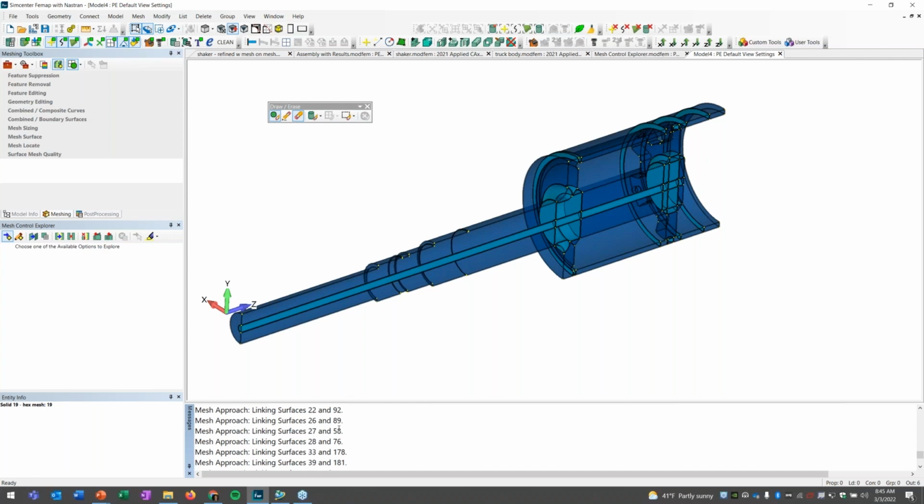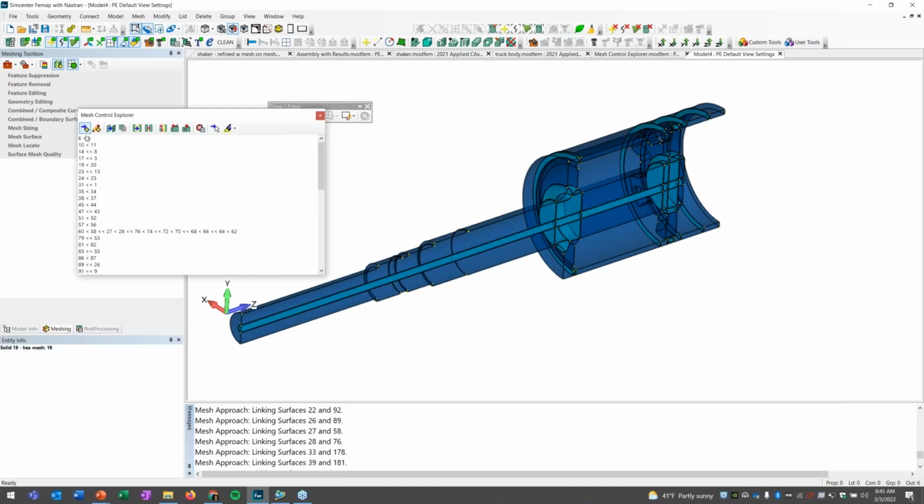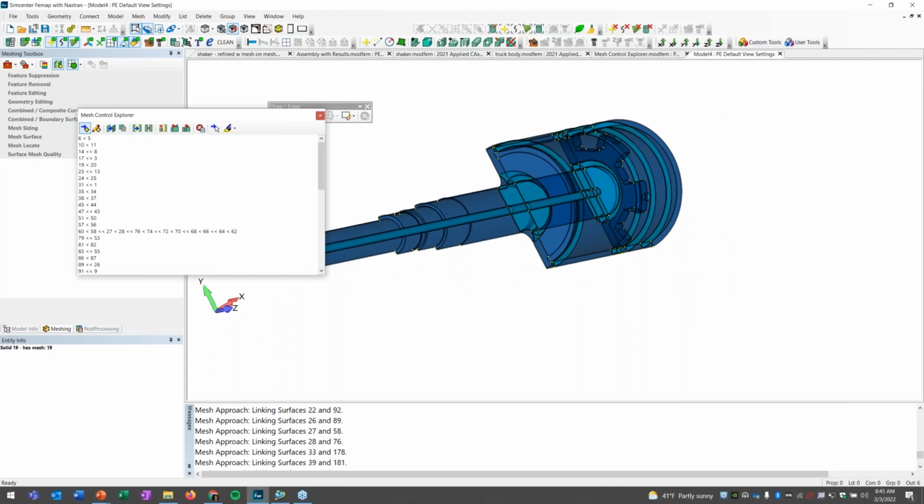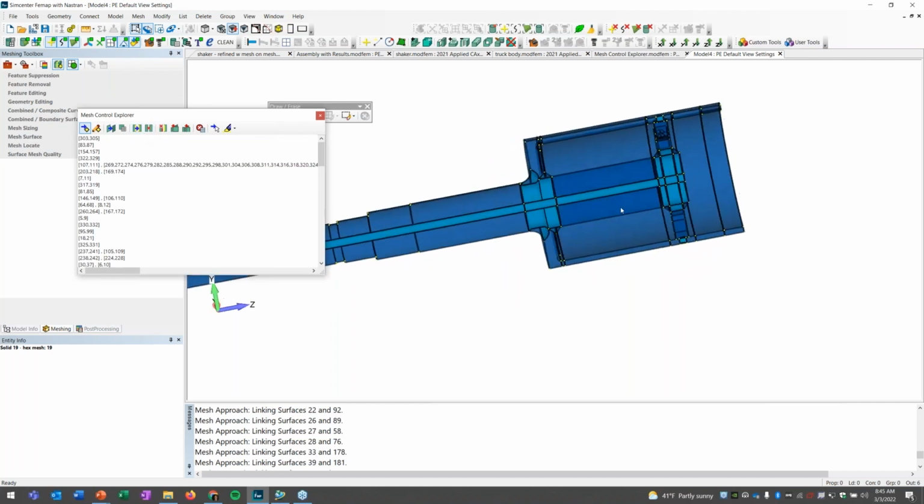None of that's new. And if you're not really familiar with hex meshing, we're going to have a dedicated hex meshing seminar coming up next. So we'll dive into some of the details a bit more. But what is new is we now have the Mesh Control Explorer to see all of these paired faces together. These are actually showing these matched faces and showing that we have somewhere to document and see where these are stored together. In terms of matched edges, that's not really necessary.